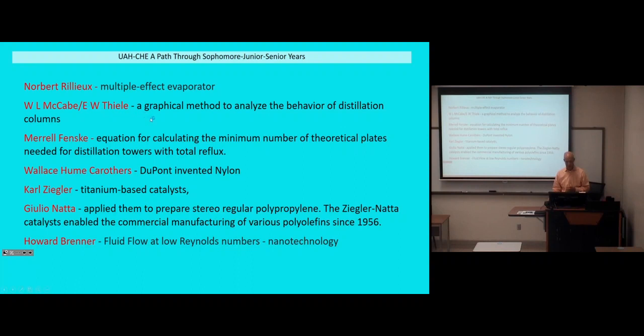McCabe-Thiele, okay, this is a graphical way to analyze the behavior of distillation columns. This was an important first step in doing this. Now we use a lot of computer simulations, but they still come back to this basic methodology. Okay? Thence, the equation for calculating the minimum number of theoretical plates needed for distillation towers with total reflux.